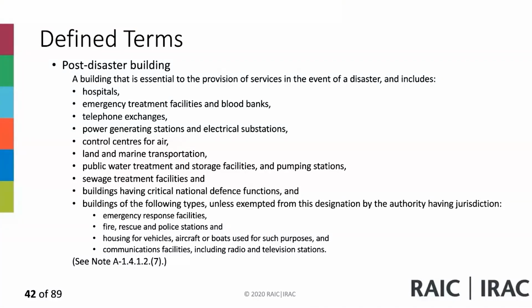In the Ontario Building Code, there is a provision that allows sprinklers to be used to protect openings and glazing instead of using fire resistance rated glazing or fire resistance rated walls. That is an alternative solution under the NBCC, and you can seek it as such, but it's not listed as a provision in the NBC.